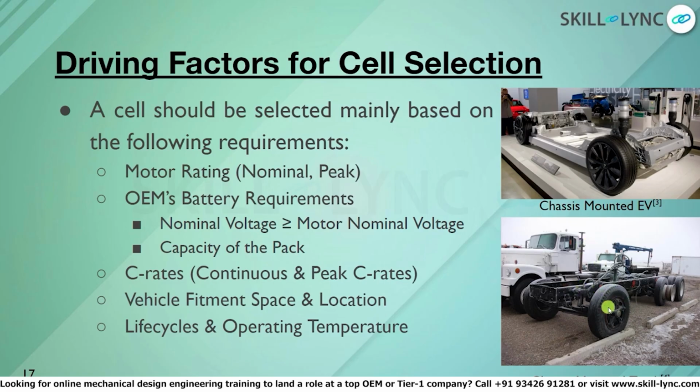If it's on the chassis, there will be a lot of radiation coming from the roads. So your pack is going to experience extreme load conditions, not just the internal heat generation, but also the road radiation. If it's on the rooftop, you will be absorbing all the heat coming on top of the vehicle. So the location where the battery pack is mounted is really important to know.